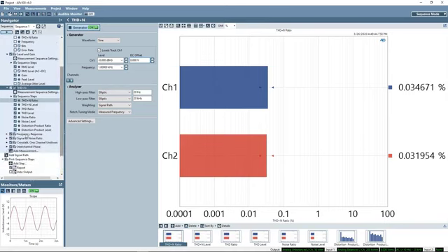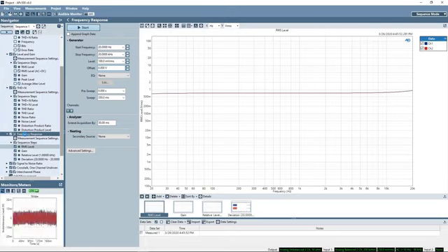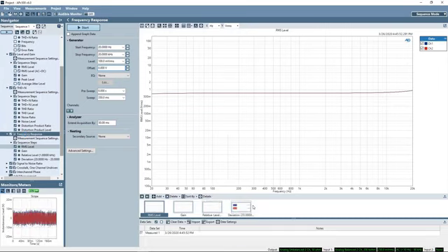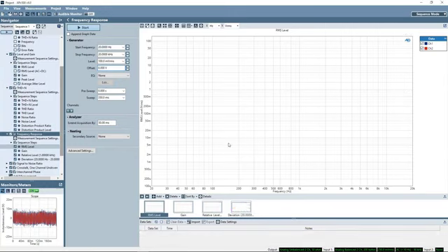Frequency response uses a chirp signal, which is a hallmark measurement in APx. It's very fast. 350 milliseconds is the default sweep time. I'll set the level and turn on the audible monitor so you can hear the chirp signal when I start the sweep.